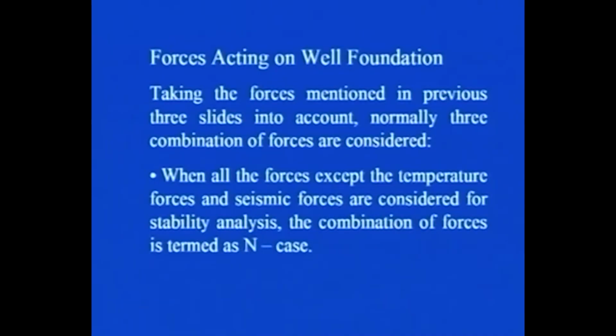Then, taking the forces mentioned in the previous 3 slides, as I told you, various forces: dead load, live load, and then forces due to the tractive effort of vehicles, buoyancy force, earth pressure, etc. Normally 3 combinations of these forces are considered. See, we have to make sure, because all these forces will be acting simultaneously. So, we have to group them. Mainly 3 groups have been recommended, and we determine the combination of forces from all these 3 cases, and the worst one we consider for the analysis purpose. So, what are these 3 groups?